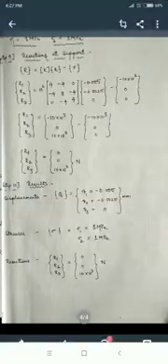Similarly, for element number 2, sigma 2 equal to E2 upon L2 [-1 1] [Q2 Q3]. Q2, Q3 because the nodes for element number 2 are 2 and 3. That's why it is taken as Q2, Q3. We know all these values, substitute them and simplify. For this also we are getting the answer as 1 megapascal. Now the second part of the problem is over.